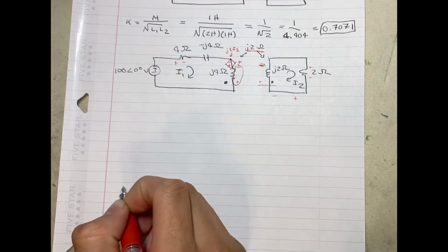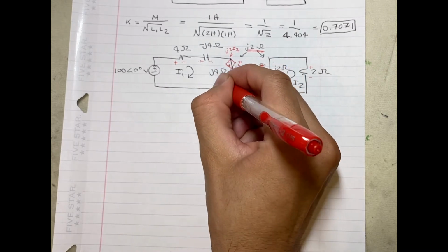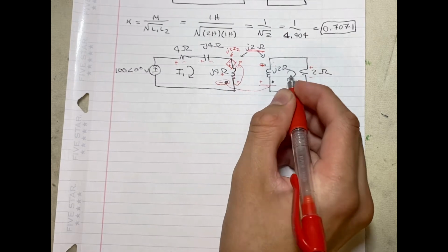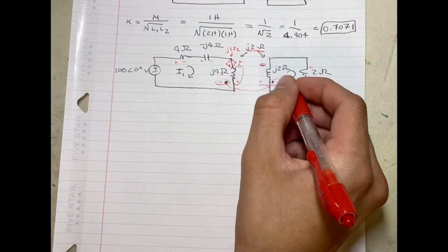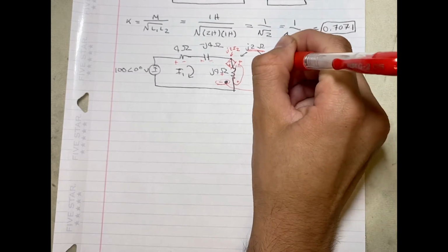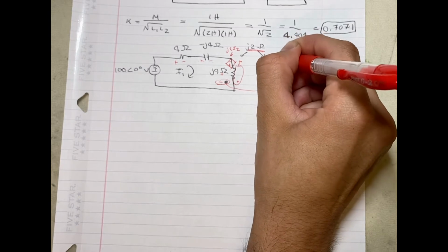Next, I'm going to measure the polarity on the left side, so plus minus, plus minus, plus minus. I'm going to pair the dot and the negative, carry it to the opposite side, mark it minus and plus, pair them together, and then shift upwards. And that's going to give me my other dependent voltage source.